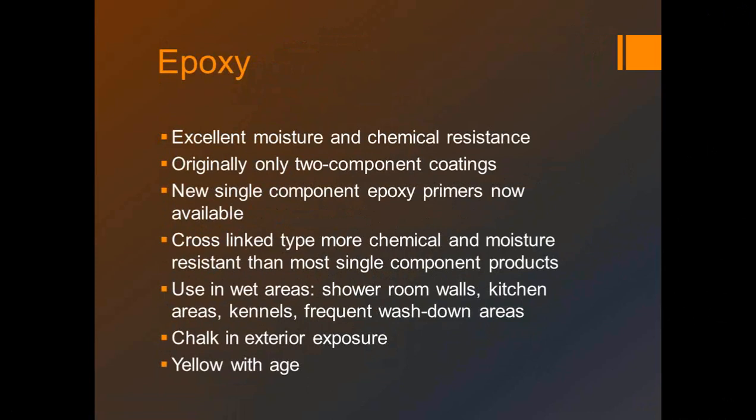And there are different epoxies. We have high build epoxies that might be better for some of these wash down areas than just a single polyamide epoxy might be. So it really is dependent upon what your needs are as to how we put these things together. And again, we're talking about finish coats here.